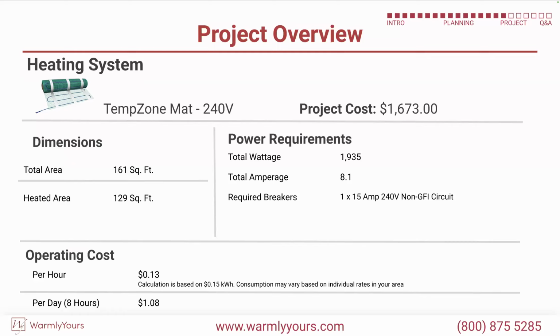So when we're troubleshooting these systems, we always ask them, brand new installation, please go down and check the breaker powering the thermostat. Is it a GFCI or not? And they go, oh yeah, the electrician said to put one in. Well, he was right, but the thermostat has it. So take that out and put a regular breaker in.